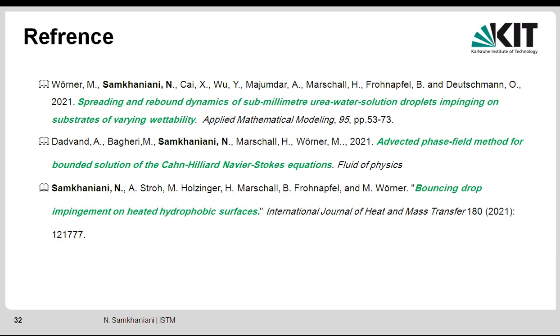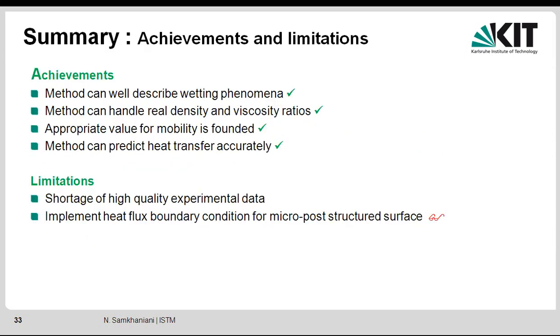We made a lot of studies. We improved the solver. You can find all the details in these references, but in summary of what we achieved here: we implemented a method that can describe the wetting phenomena, the hydrodynamic part is well described, and it can handle real density and viscosity ratios. We found an appropriate value for mobility for this kind of simulation, and also our method can predict heat transfer accurately.